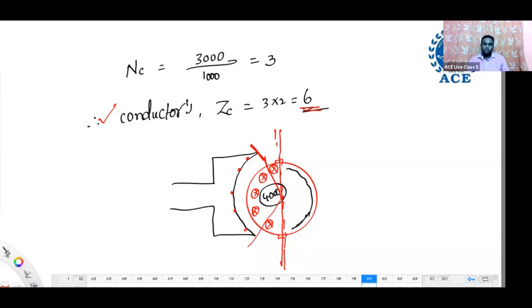See, the compensating winding cannot compensate the 4000 totally. It will compensate only in the polar region. Polar region is the pole arc or pole face, whatever is there. How much is there? 75% only. Now, out of the 4000, 75% is 4000 into 0.75, which is 3000. Means out of the 4000 ampere turn per pole, the compensating winding will compensate 3000.